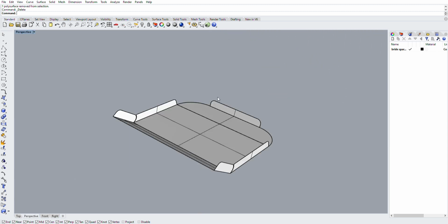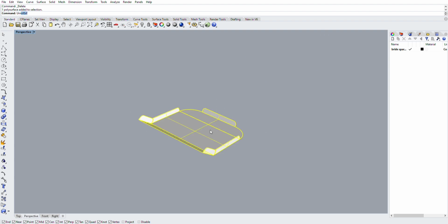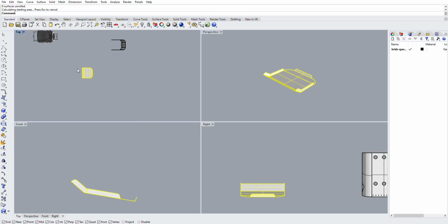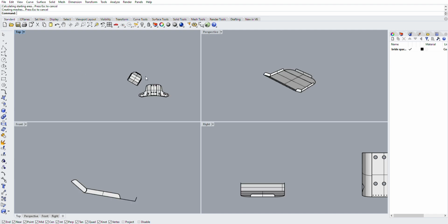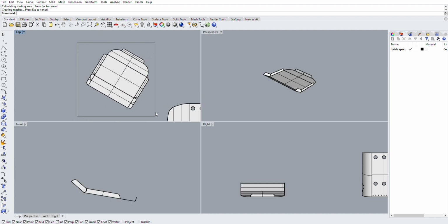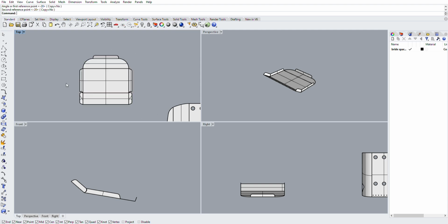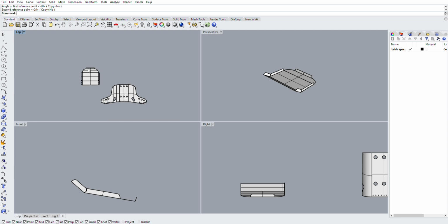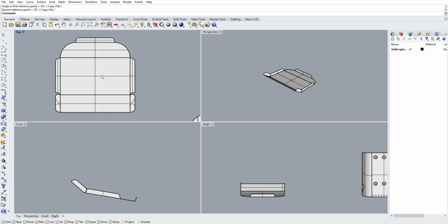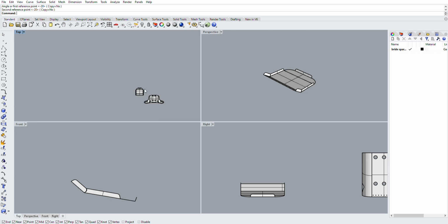And if we grab that base piece and we do the surface unroll tool, same as we did on the back piece, what we're given, and let me zoom out and I can zoom back in here, is our flange, the way that it is supposed to look. Now that is the piece completely broken down. Now obviously these are just surfaces. There's no polylines here. It's just a plain surface, and that doesn't help the plasma cutter at all.